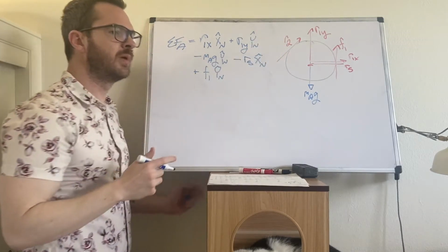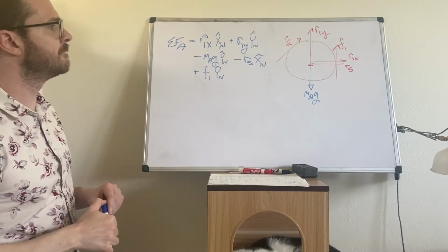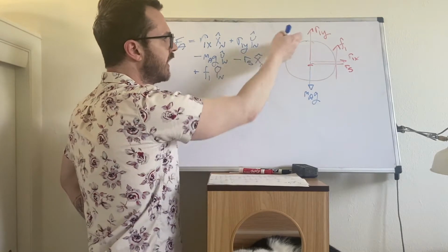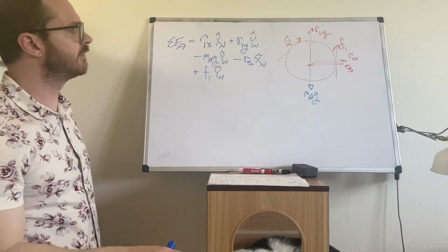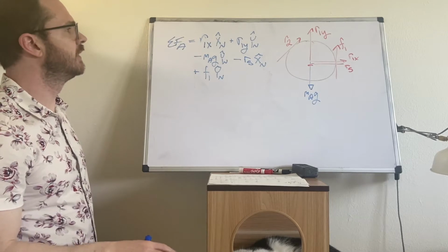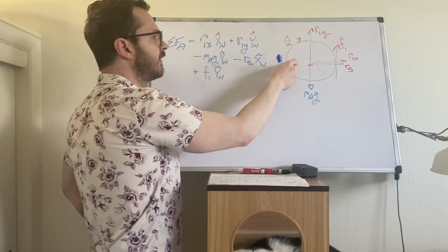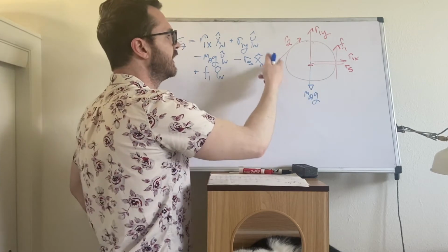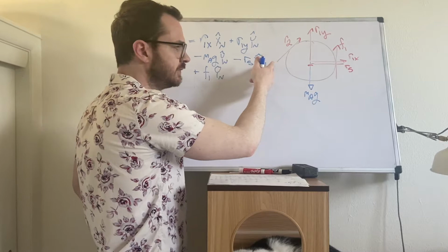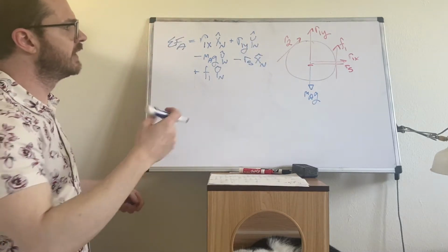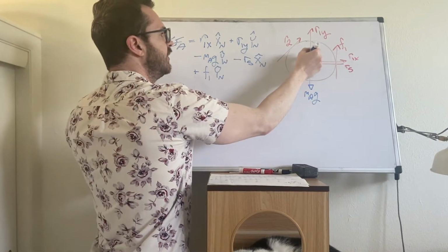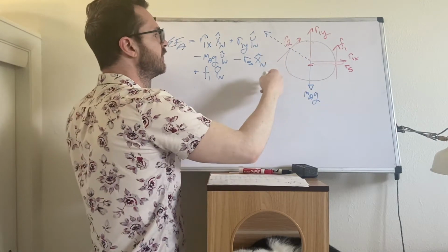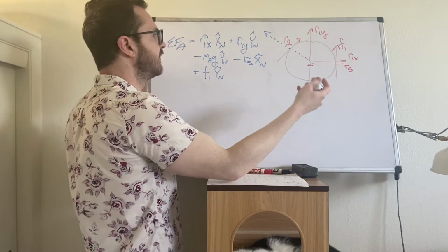And what do we need to do about R2? We need a direction for R2. It's not aligned with the N frame, and don't rotate the N frame to make it align, but also it's not aligned with the A frame because the disk is spinning, so the A frame is constantly rotating. The direction of R2 does not change. What that means is, what is best is to make a new frame. It's a non-moving frame, so it's just been offset from the inertial frame by some fixed angle.